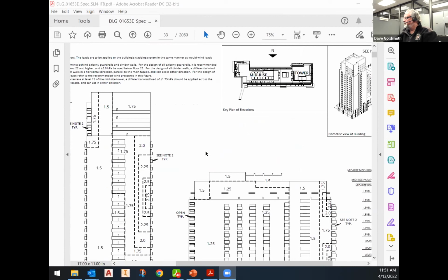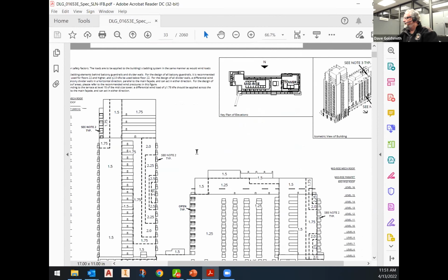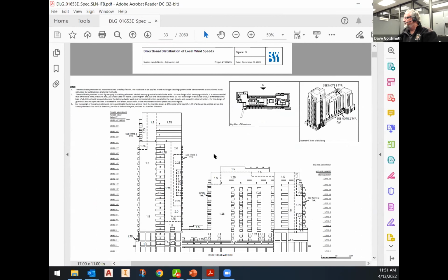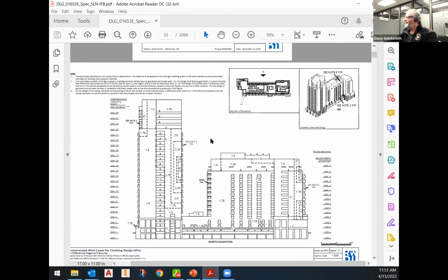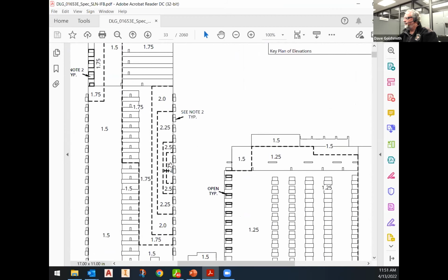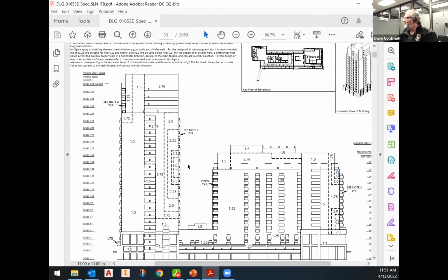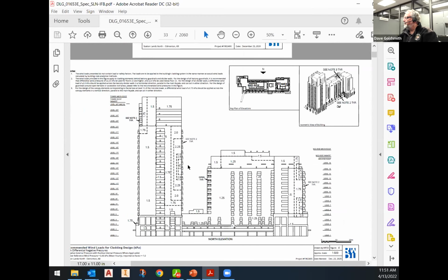So these were the results of the wind tunnel testing, and it's giving you the highest pressures in kilopascals. And you can actually see, counterintuitive to what structural commentary does for simplified static methods, it's not necessarily the top floors. It tends to be the corner windows in areas such as this. So our highest pressure is 2.75 kPa on this building.